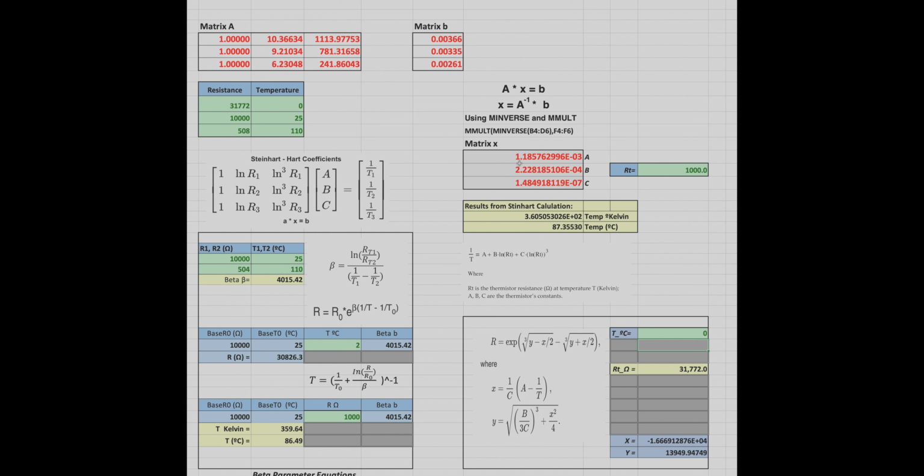Well, by Kirchhoff's voltage law, we know that the applied voltage minus the voltage that we're going to measure must equal the voltage across RT, because the law says the sum of the voltage drops is 0. So if you know one voltage and you know the applied voltage, the other voltage, in this case, the second resistor RT, is the difference.